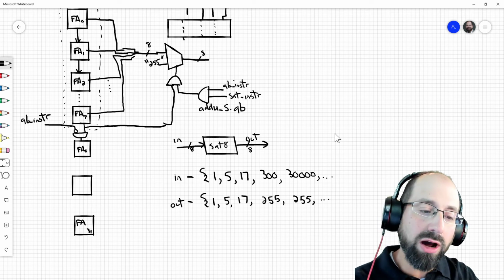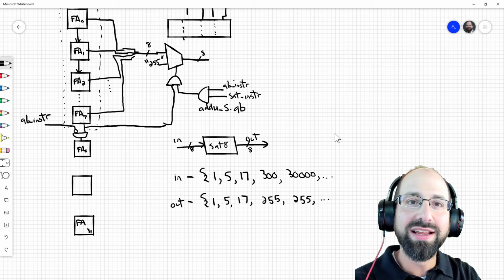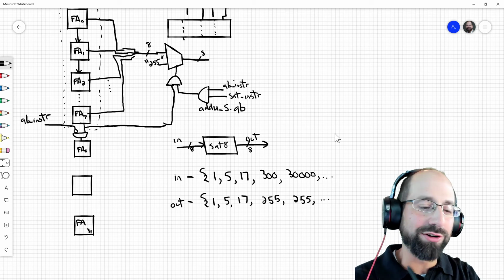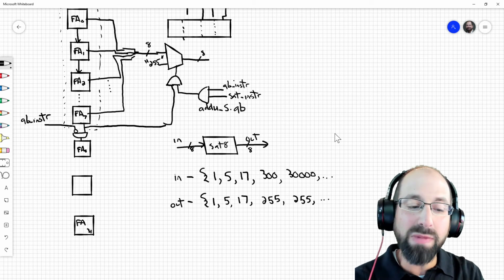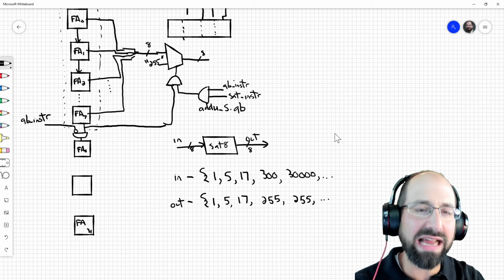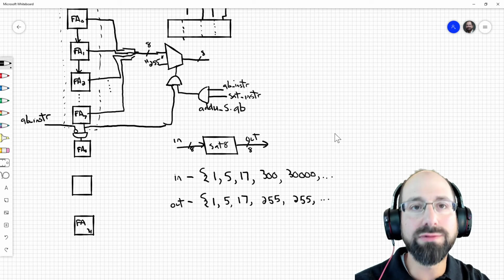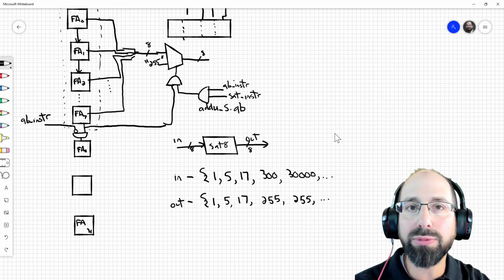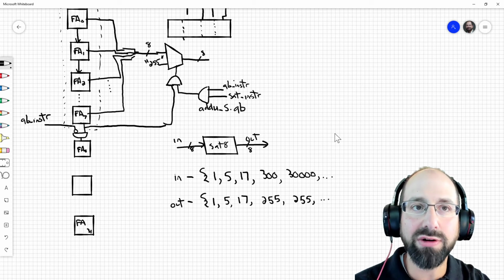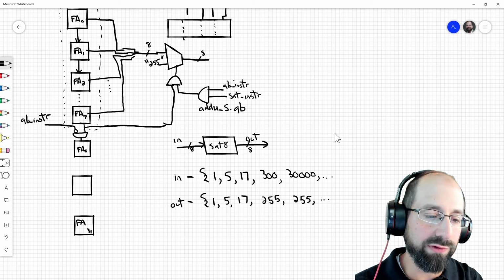Because you can have quad byte instructions that are not saturating instructions, but given this definition, there are no saturating instructions that aren't also quad byte instructions. So you may not need that second AND gate there, but conceptually it's the same. It works out exactly the same, in which we should take 255 only if two things happen. It was a saturating operation we requested, and the result actually necessitates that saturation because it was larger than what could be stored in 255.